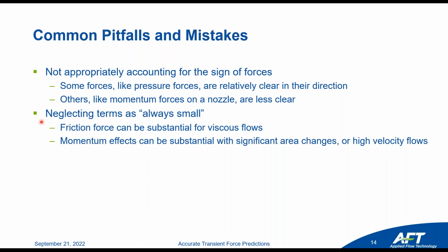And there's really no way to know ahead of time if these forces, friction or momentum, are going to be substantial enough that they're going to impact your reactions substantially, and maybe change the conclusions you make about what kind of support you need. So our argument would be, yes, sometimes pressure times area is fine, but you really don't know until you actually do it the right way. So don't guess, just do it the right way the first time.